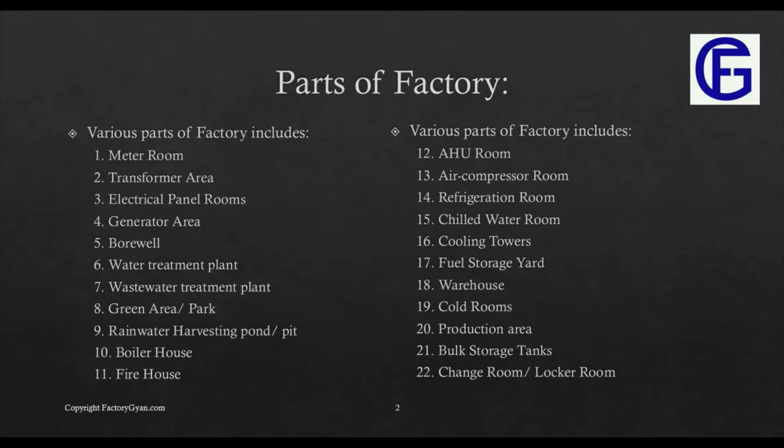Then, after you have used the water, it will go to a wastewater treatment plant where you will treat this water before discharging it into the environment. So, as per your consent from the Pollution Control Board, you might discharge it after treatment into the green area, or you might have to have a zero liquid discharge plant, ZLD plant, where you have to evaporate all your wastewater, and you cannot throw any water into the environment. So that kind of arrangement depends upon your consent from the Pollution Control Board.